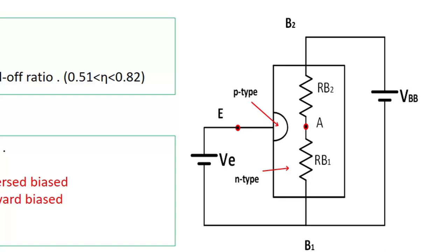The reason is that when a positive voltage is applied across the P-type, it injects more carriers across RB1, and as the number of carriers is more in region AB1, the resistance RB1 will reduce. As it is a semiconductor material flooded with more carriers, its resistance reduces. As RB1 reduces, RB1 plus RB2 will reduce, because RB1 is the major portion of this internal resistance. Then current will start flowing from B2 to B1. We can say our transistor is completely on.